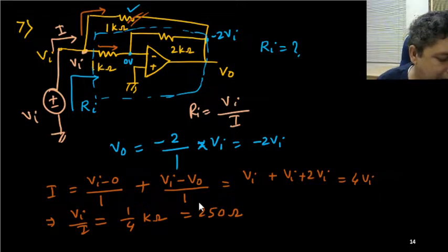One thing is that a differentiator is not unstable. Integrator could be an unstable circuit. If you don't connect extra resistance, then it would be unstable, meaning marginally stable. If you consider the integrator, you will be getting one pole at origin.